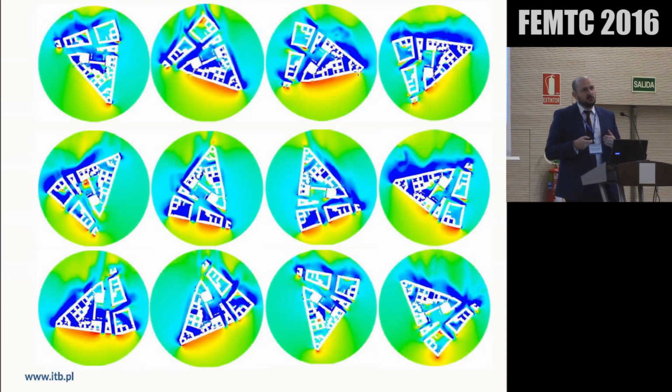Because you need to find a scenario in which you have the lowest pressure on your inlets and the highest pressure on your outlets. That pressure difference between inlets and outlets will determine the performance of your system. And you don't really know before you do that how it will work on your building. This is why you have to introduce some wind angles.